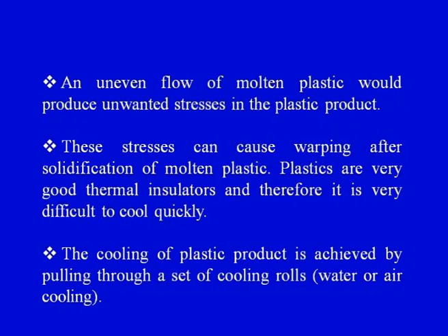An uneven flow of molten plastic would produce unwanted stresses in the plastic product. So we have to ensure that the flow of the plastic in the molten stage should be very uniform. An uneven flow would result in certain stresses which are completely unwanted, and if these stresses are present in the product, after some time the product may fail because of these developed residual stresses. So these stresses have to be avoided in any case.